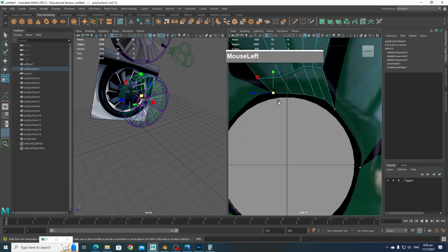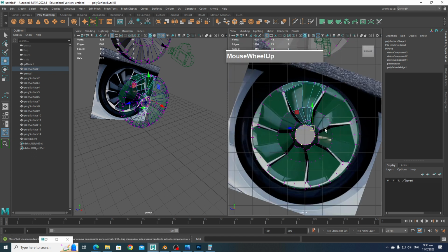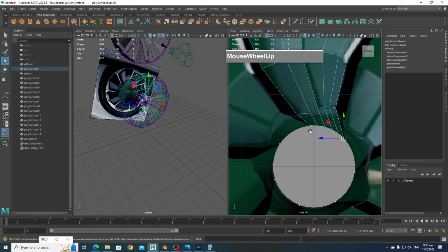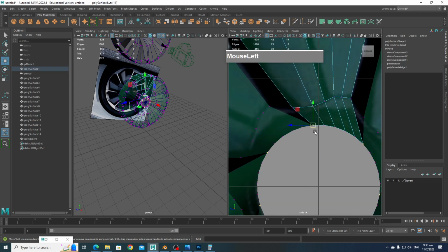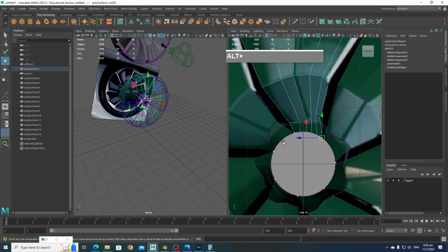I'm going to select one vertex here, press W to move, and holding down V, we can snap it to one of the vertices here, then this one to here, this one to here, this one to here, and so on. So now I can see everything is matching, although maybe I want to snap one step forward instead. So there is one way, holding down the V and dragging it as you move it. So now we know for sure this is definitely going to fit.